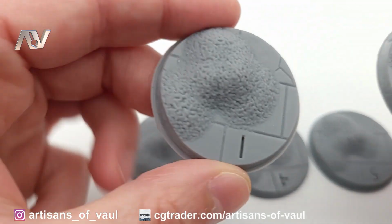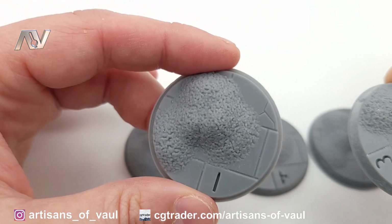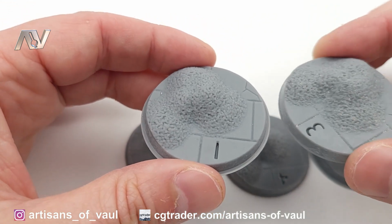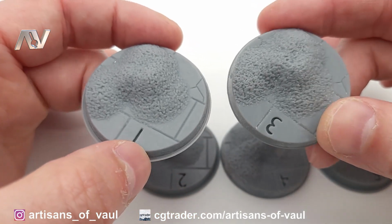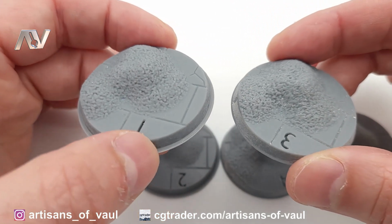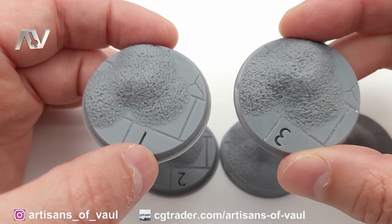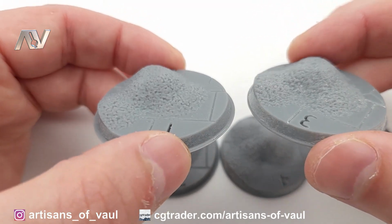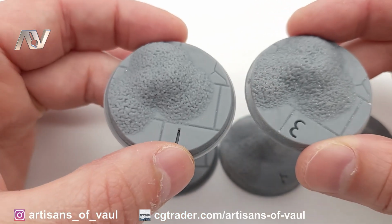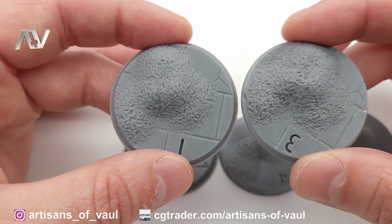So we were expecting 1 to be a bit more granular, show the texture a little bit better because of the geometry nodes and the instances that were made to create this, but really, actually it doesn't look very different to 3. I was actually quite surprised at this. They basically look identical. There's a little bit extra texture on 1, but not by much. And I would say that I think the extra effort that it takes to put 1 together, and especially to boolean the points together, which I didn't show you on screen, it was a real pain. It's just not really worth it. Look at them, they're almost identical in texture.